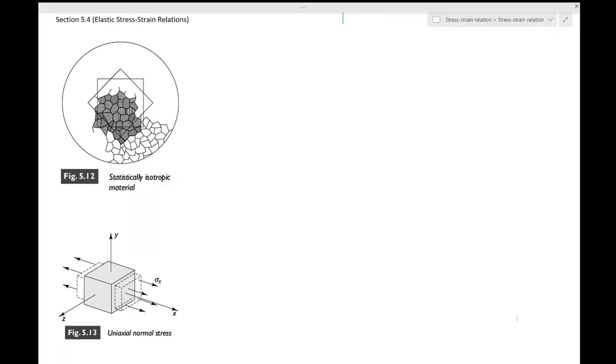As is mentioned by the author in your textbook, in the preceding sections, stress-strain relations were considered for the special case of uni-axial loading. Okay, so if you recall the previous classes of this chapter, we have only referred to this one-dimensional case, uni-axial case, and we did a tensile test at the start of it to be able to draw graphs and then idealize those graphs and eventually learn about plasticity. Okay. Now, only one component of stress, the axial normal component, was present, and only the axial normal component of strain was considered, sigma x and epsilon x, if you recall.